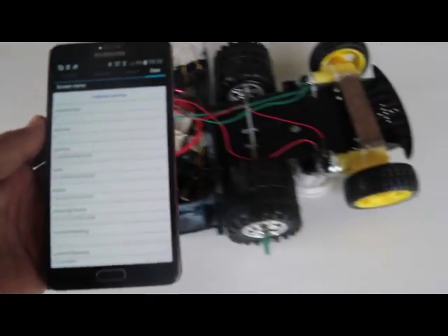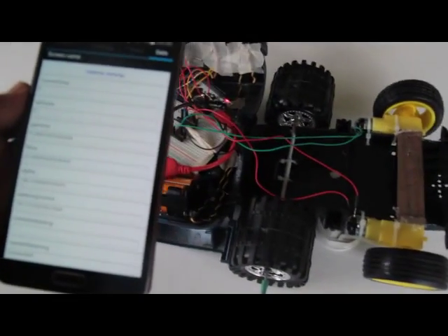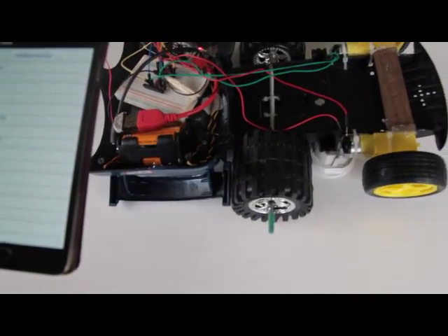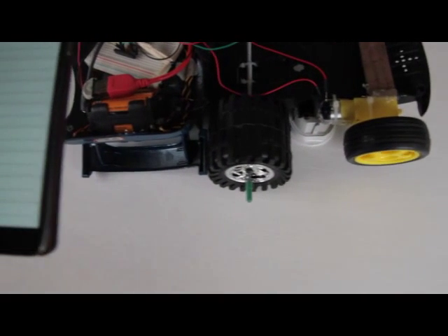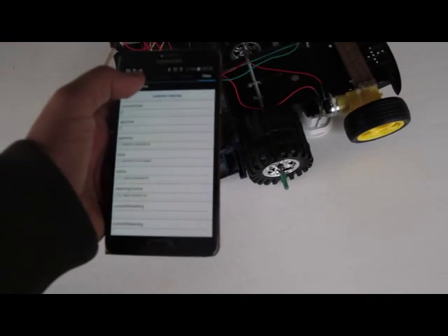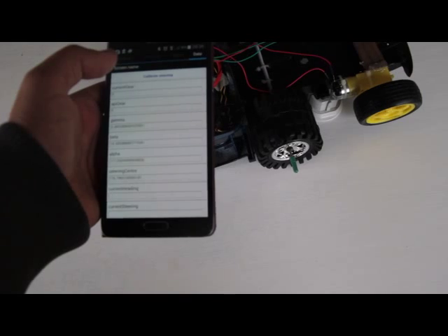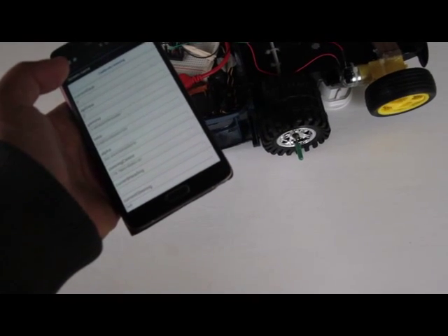Okay, so if I hold the phone at a relatively flat angle, about 10 degrees. I also need to calibrate the steering. My alpha is on 195. I'll get it to roughly 180, and then I'll just tap the calibrate steering button. Okay.